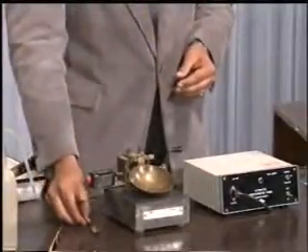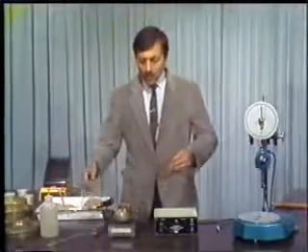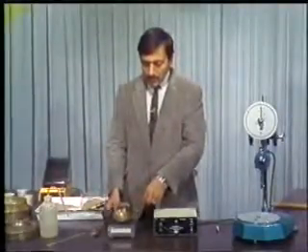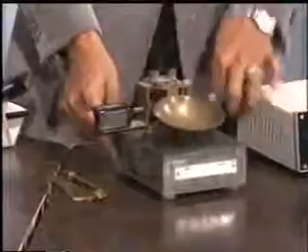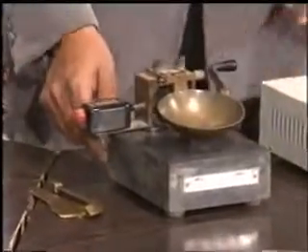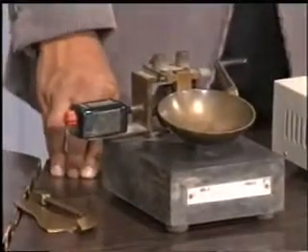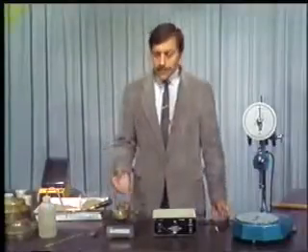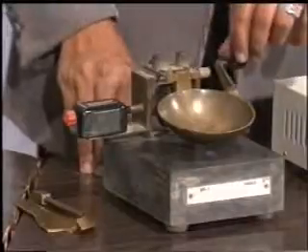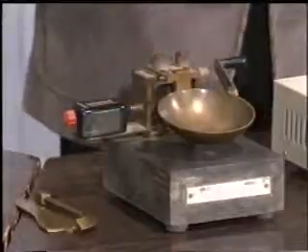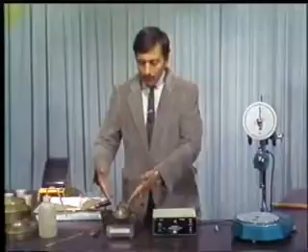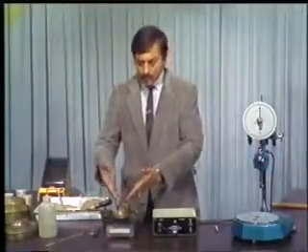The soil is then allowed to flow from both the sides by giving jerks using this knob. Now, the liquid limit as per this determination is that water content at which, if the soil in this cup is given 25 number of blows, the two parts of the soil will flow towards center and just meet.